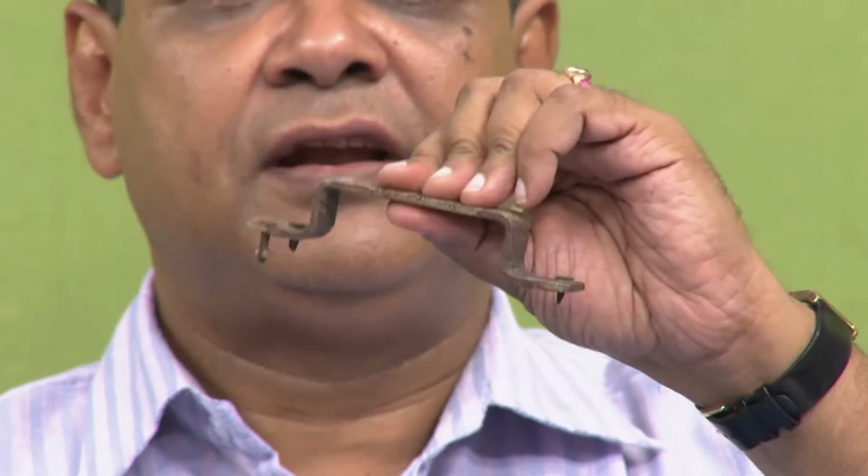So, this again can be explained from the point of concentration difference of oxygen. This is a classic example, you might also see such things happen at several locations. Now, this is what I wanted to say, that concentration cell is a serious consequence. Even crevice or pitting corrosions, these two are very serious forms of corrosion, as we have explained before, because they are extremely localized, and they are also related to the concentration difference of oxygen.